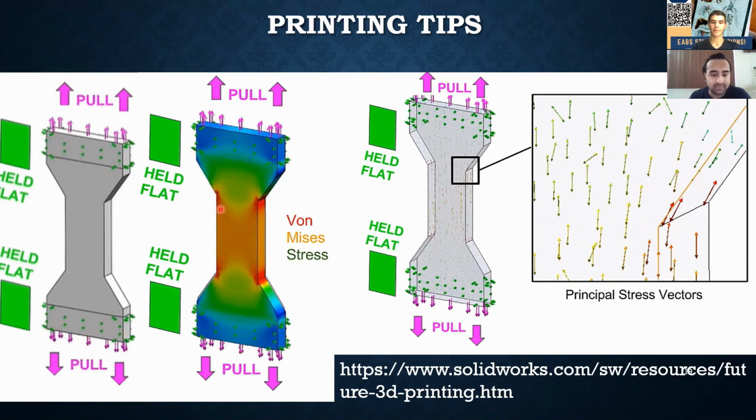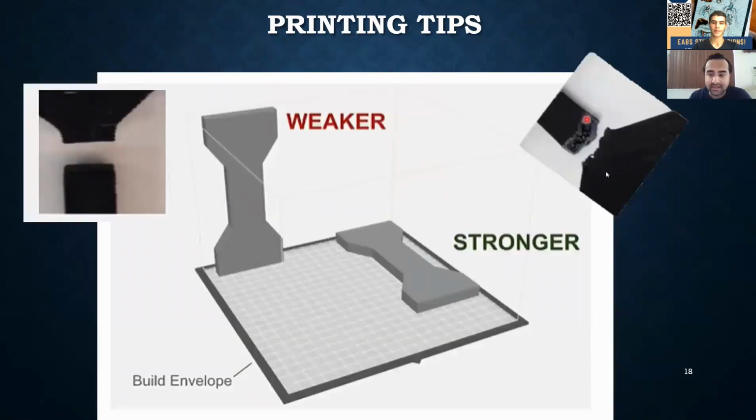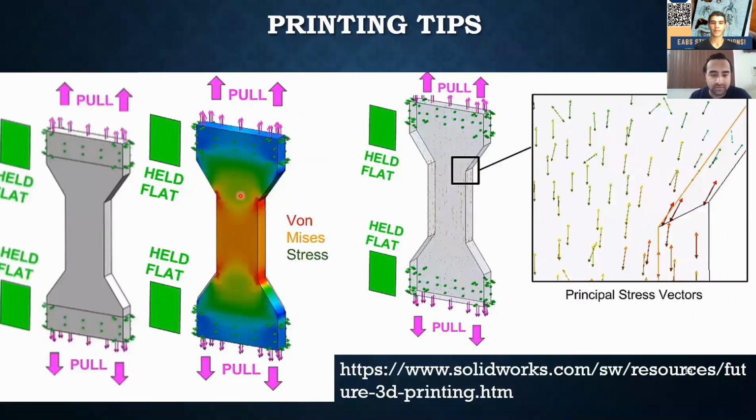And you can see you have a stress concentration building up here, and the stress sort of occurs vertically. So you can also take a look at the orientation of it, and you can see here that the orientation for the von Mises stresses are occurring vertically. And if you notice here, the edges are where it's concentrated at, and that's exactly where it broke off over here. But the internals, you can see by this sort of parabolic shape, the internals seem more structurally rigid, which is what you got here. So there's less stress occurring inside than outside.